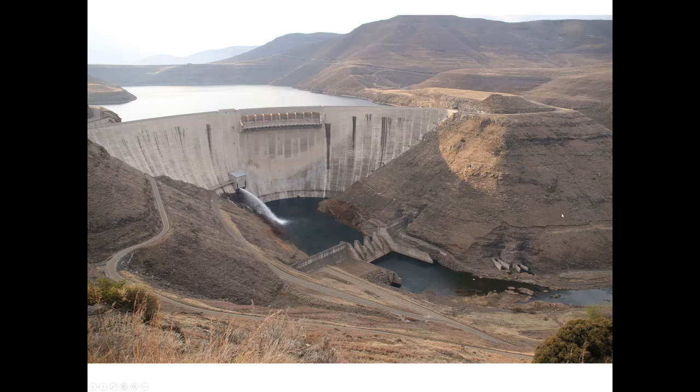The original idea was to build the dam from the lava or basalts from Lesotho. But it was very quickly realized that if you excavate the lava and leave it to the atmosphere, it undergoes so-called deuteric alteration, and it basically started turning into mud. So then we had to find the dolerite intrusions in the lava, and they have basically the same composition, so it was very difficult to distinguish between the two. But eventually the dam was built with dolerite.